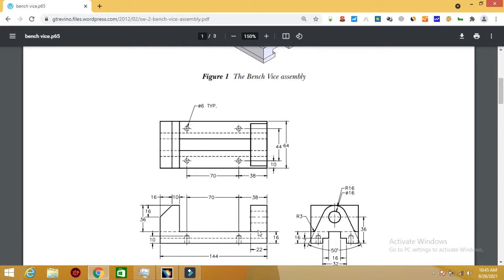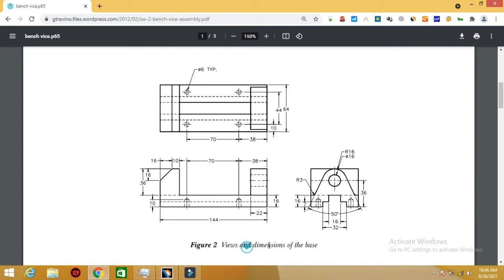But from this diagram and this diagram, if you study the front view and the side view, it becomes clear that this is not a rectangular flat portion, this is a curved surface. So we'll make it separately afterwards. I have already explained the CATIA tools, so let us make this shape resembling this shape, and progress and make the base part in CATIA.